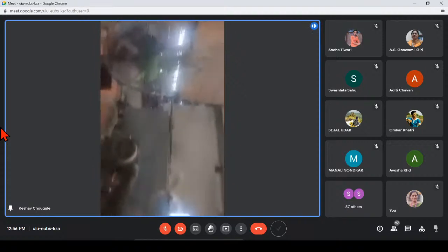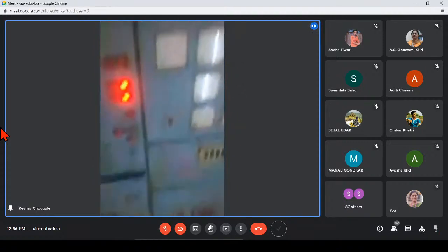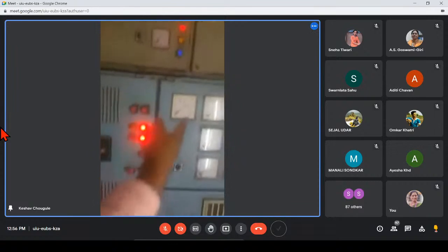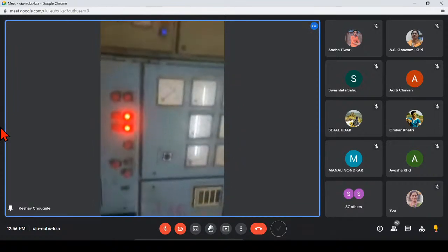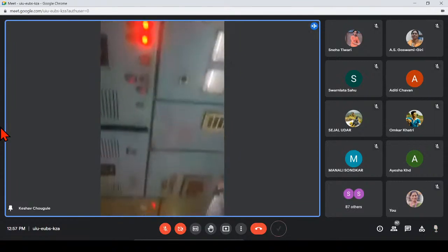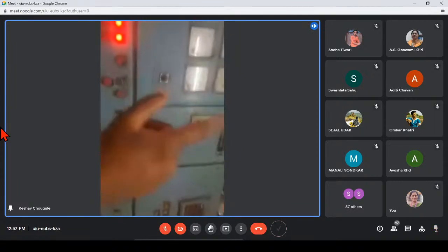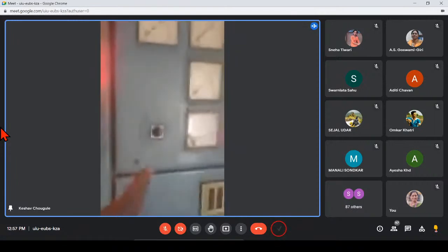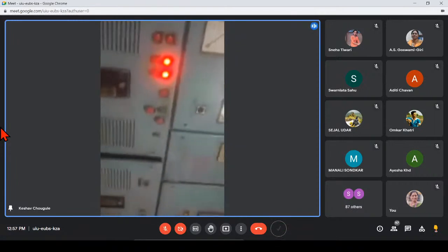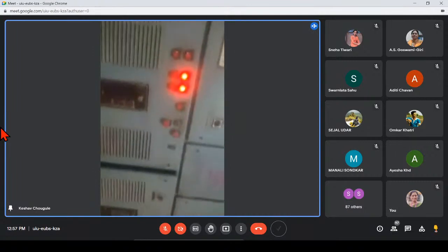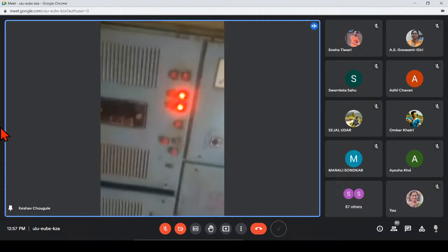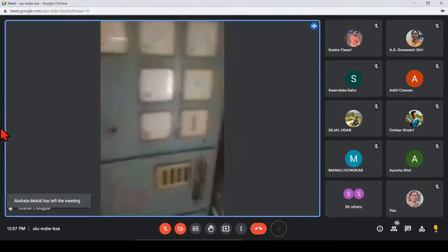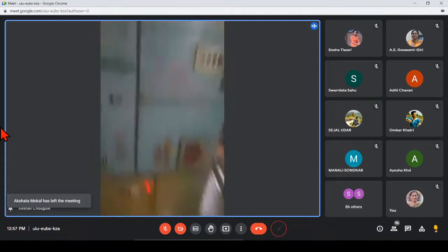The generated power from this alternator and steam turbine is live here. See, here are the ampere, volt and power factor of this sugar factory. There is the ampere reading. That means almost 2500 kilowatts of electricity is generated by this alternator, and a pure 440 volts of power is generated. That 440 volts is the pure voltage used to drive motors from 2 HP to 250 HP. And this is the power factor of the generated electricity.